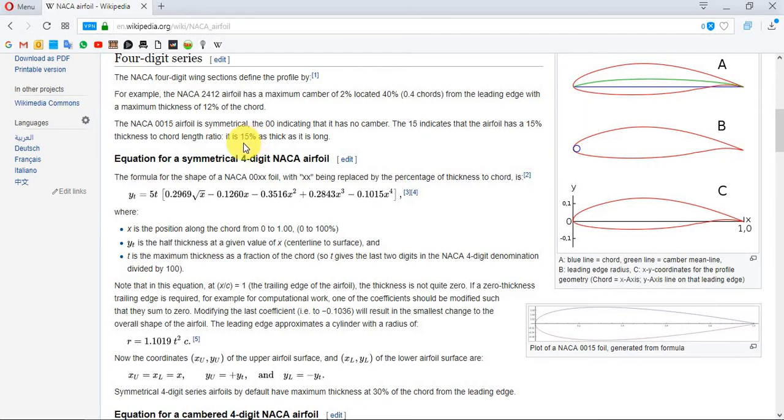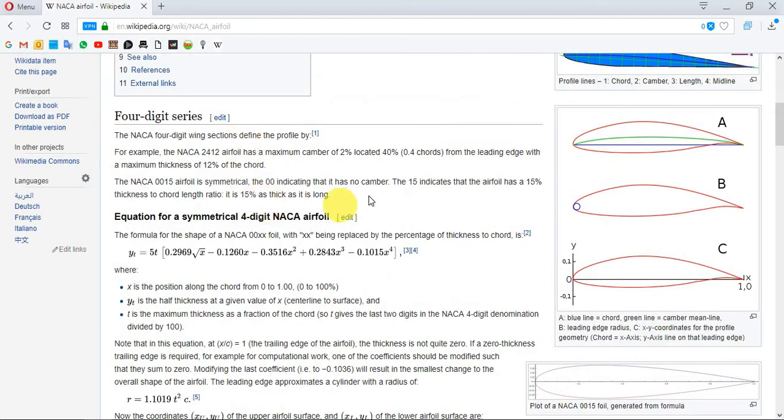Whereas with these NACA airfoils, there is a lot of empirical data out there because they have been tested again and again and again. So you can see you have your empirical data and all the graphs that you need in order to make a more reasonable prediction of what you're going to get out of your lifting surface in terms of lift and drag.